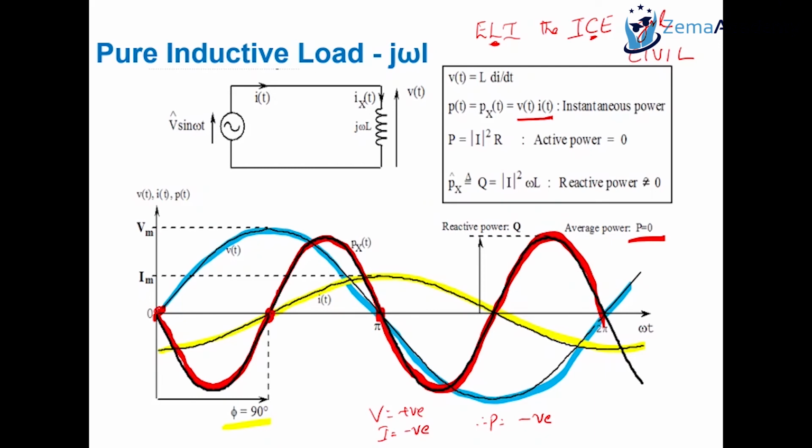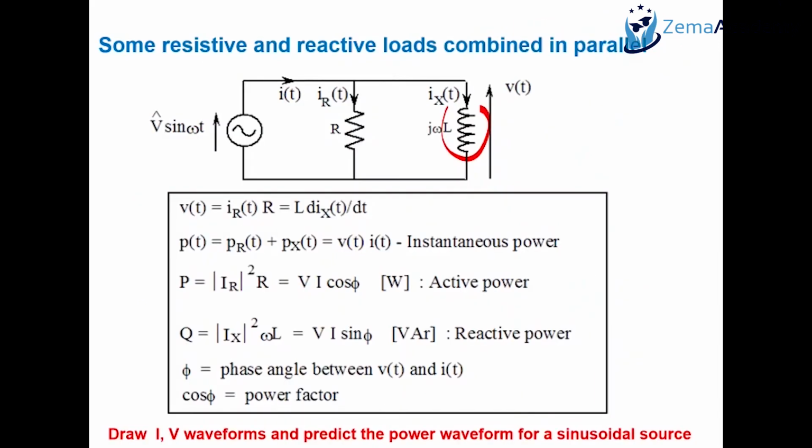Yeah. So in real life, most loads are like this, which they have a resistance and a reactance. There might be more resistance, less reactance, more reactance and less resistance, but it's always a combination of those two. And the reactance can either be due to an inductor or a capacitor. For example, if you have a compressor in your refrigerator, which keeps things cool, that acts as a source of inductance. So that's an inductive load. Your motors, they're all inductive loads. They have certain inductance values with them.